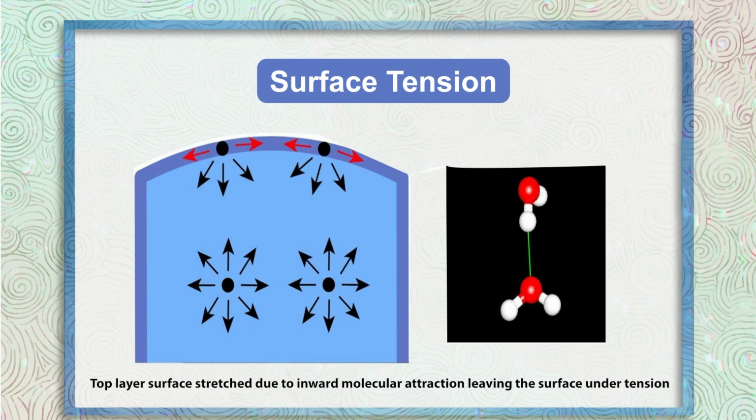If you want to understand the surface tension, the best way to do is to put a small steel pin on water, and it will not sink. The reason for that is the tension which is there on it. Even though the density of steel is very high compared to water, normally it will sink, but the pin that you put there is able to stay, as its weight is compensated by the tension the water has, and it will not sink.